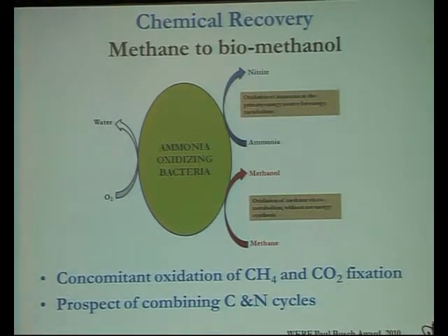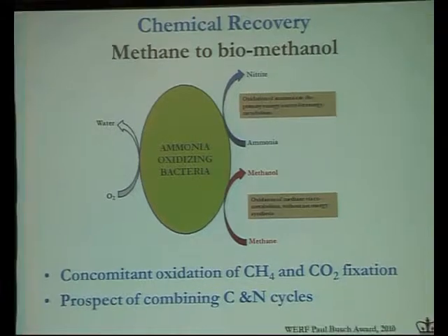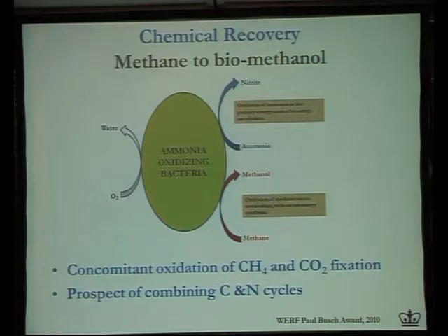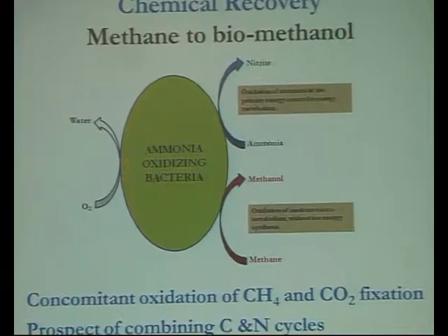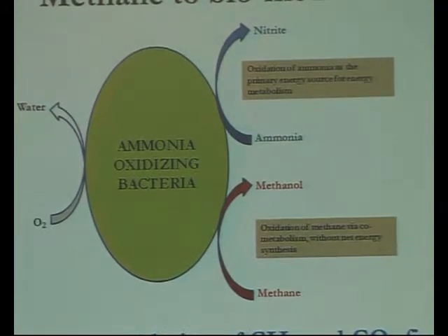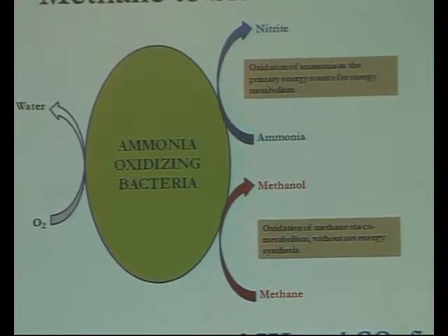I'm just producing methane, I can make cooking gas, right? Where is the ammonia coming from? Where is the methanol coming from? But I can answer this. The carbon is going to methane, and the methane of course can be used. Where is the nitrogen? Like I said, in digestion, just the carbon is redox cycled, it's reduced. The nitrogen and phosphorus are not redox cycled. The nitrogen is just coming straight out. So now what we are doing is taking the nitrogen and oxidizing it and using that to oxidize the methane to methanol. What do I do with the methanol? Produce biodiesel. So we are closing some of the loops here in terms of the overall process efficiency, the overall process yield, and the overall process kinetics.